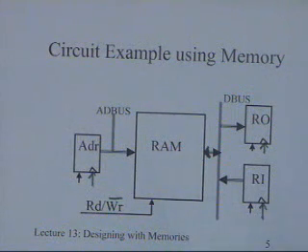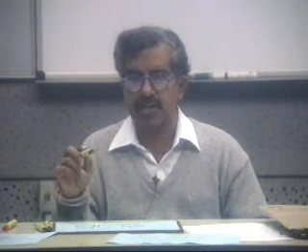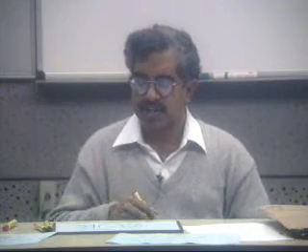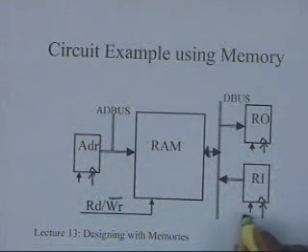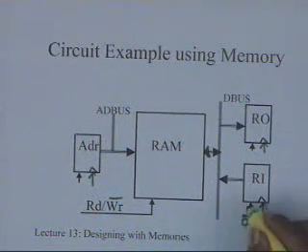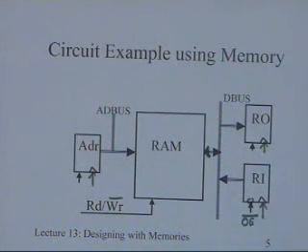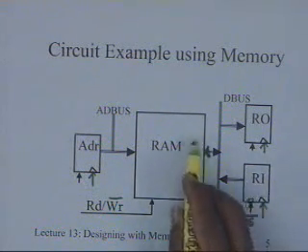In any particular write cycle, I have to decide which particular device is supplying the data. That can be done through one of the output enable bus, implying that only one of these registers will be enabled.